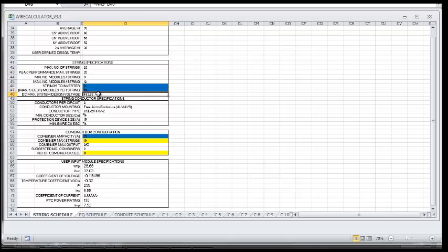So based off those parameters that we have so far, module, the inverter, temperature, this will help us calculate our strings, both the size of the strings of modules connected in series and the number of parallel inputs that we can have to the inverter. So you can see there it turns red when your inputs are not within the allowable parameters. Those parameters are shown just above there. So when you're within the tolerable range, everything should stay in blue. Okay, so the yellow has a problem, red has a problem, so let's set those back where we need them.